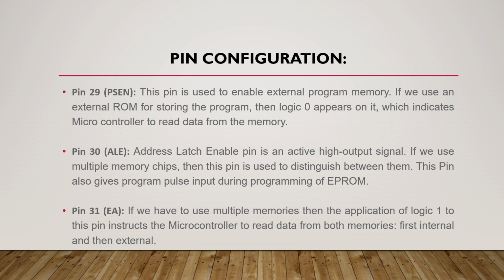If we give logic 1, it sends an instruction to the microcontroller, and the microcontroller will understand that instruction to read the data from both memories, the microcontroller's own memory and the external memory we connect. So both sets of data we have to read by using pin 31.